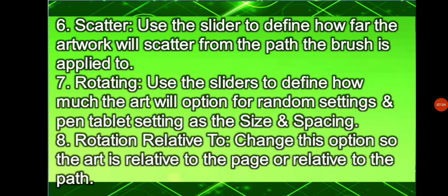Number 7 is rotating. Use sliders to define how much the art will rotate as the brush is applied to the path. Use the same option for the random settings and pen tablet settings as the size, spacing, and the scatter.